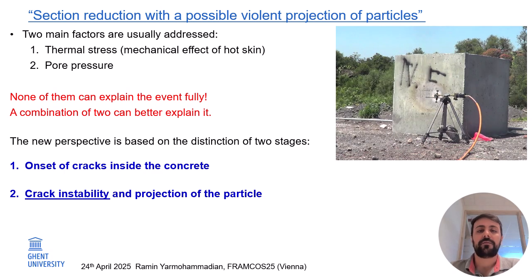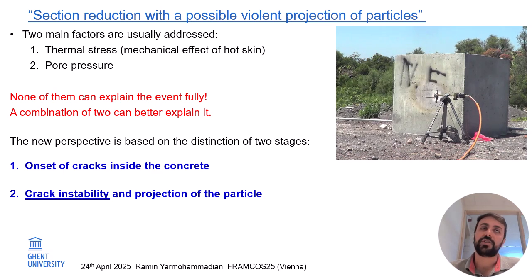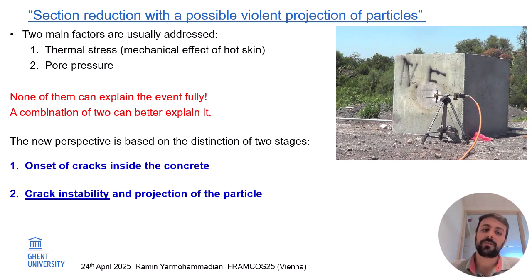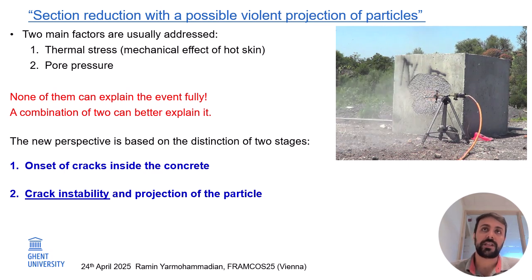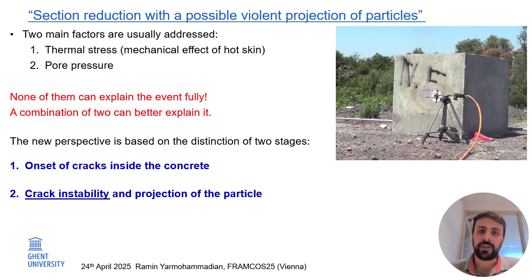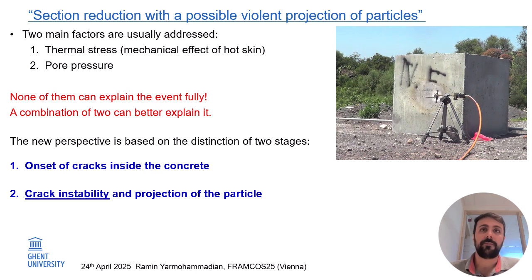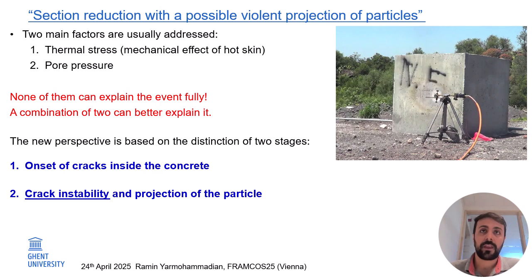But unfortunately, neither of those mechanisms can explain the event fully. So a new mechanism based on a combination of the two can help us understand it. In my PhD, I presented a two-stage mechanism in which we distinguish two phases in the whole event: crack initiation, followed by crack instability. This idea is inspired by the many stable cracks found in post-fire assessments of structures.